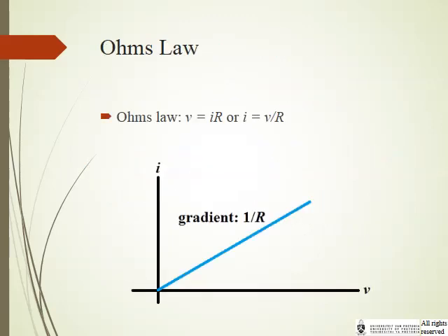Moving on to Ohm's law. So we've already spoken about Ohm's law, and we always have this joke in electrical engineering that everything in electricity is Ohm's law. And hopefully as we go through the course, I'm going to show you the whole time, see Ohm's law, see Ohm's law. So what do we have? Voltage equals current times resistance, or then obviously we can write current equals voltage divided by resistance. Now lo and behold, for some reason some students still get this wrong.